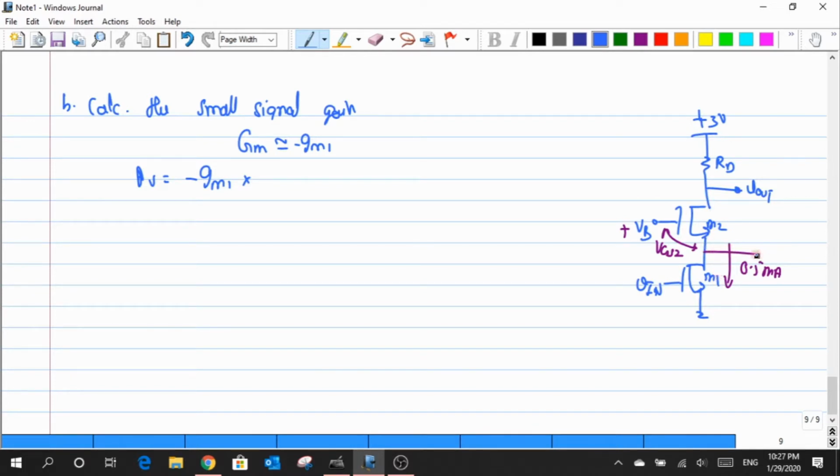So the resistance that I have between the drain and source of M1 is basically RO1, and when I look through the drain of M2, we know that it gets magnified. So we'll use that concept for the downward direction. Currently I denote that expression as Rx, which is gm2 RO2 RO1 plus RO1 plus RO2.